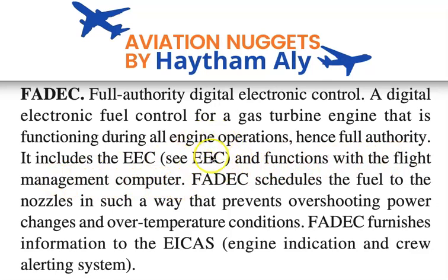The EEC will function with the flight management computer, because the engine controller, or EEC, always needs data from the flight management computer to allow the engine to fly the aircraft in its computerized profile.